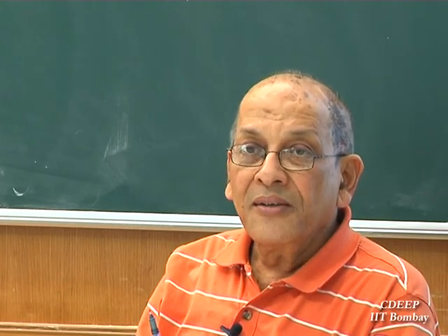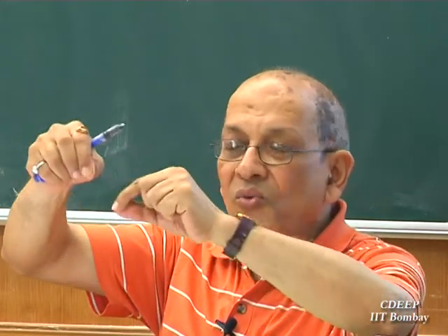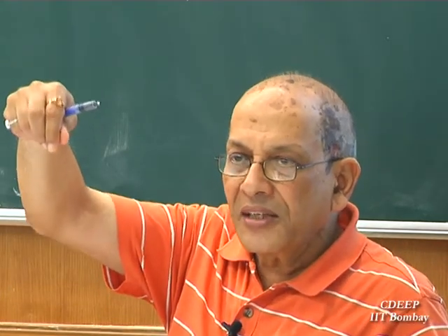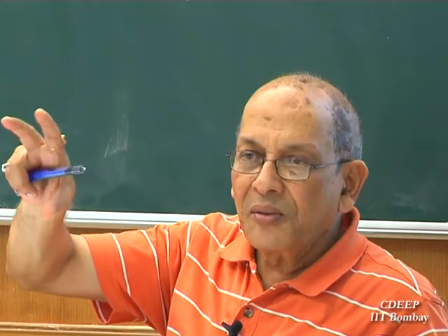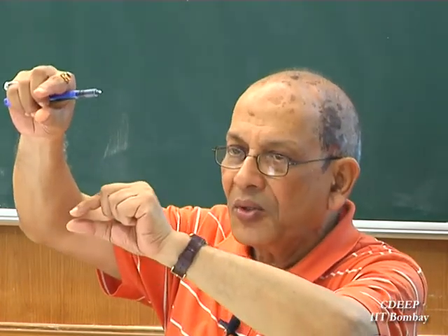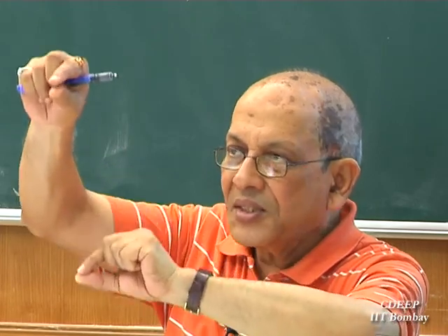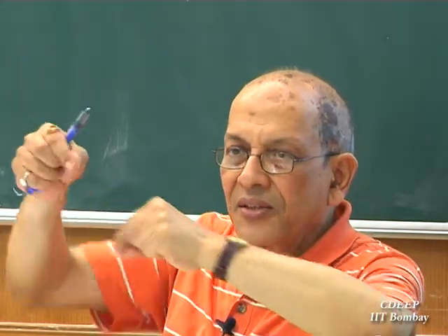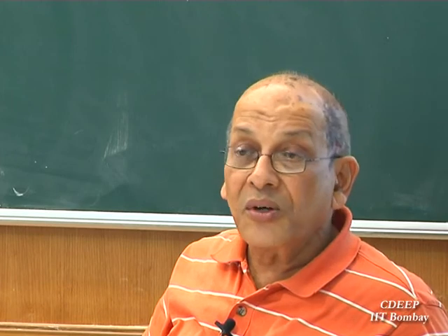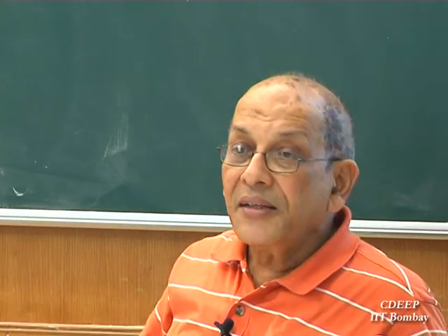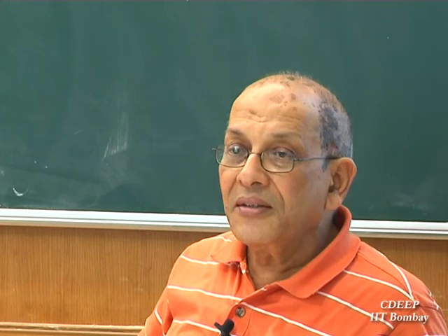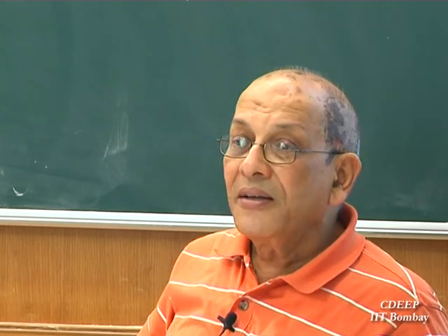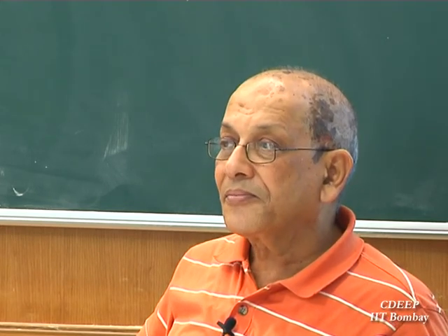It will start flowing, and plasticity grows. I think I have told you also about ultimate load analysis: find out the ultimate load of the beam, how plasticity grows from top to center. It starts at the top because of maximum stress, and then it grows inside. So once the material starts flowing at one point, it will spread and the entire member will fail. So this is for designing, to make a safe design. Everything that we are doing is for safe design of structural elements.